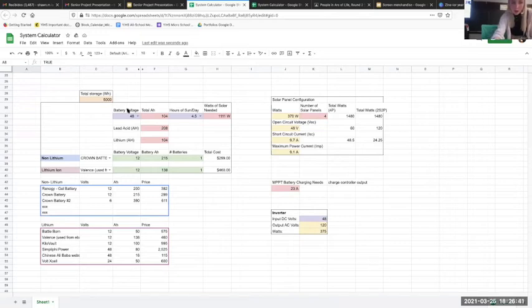So here we have the rounded up total storage that I need to make for my system. If I'm choosing a battery voltage, it's better to go bigger, because if your voltage is higher, your current can be smaller, and everything else can be smaller with that. We ended up deciding on a 48 volt system, but I'll show you later what it looks like with a smaller system. Once you have your voltage and your watt hours, you can find your amp hours, and that refers you to what kind of batteries you're going to use. But we're going to go over to solar panels first.